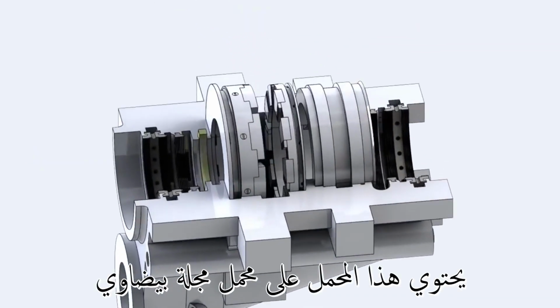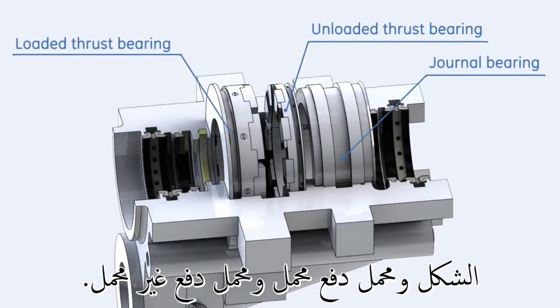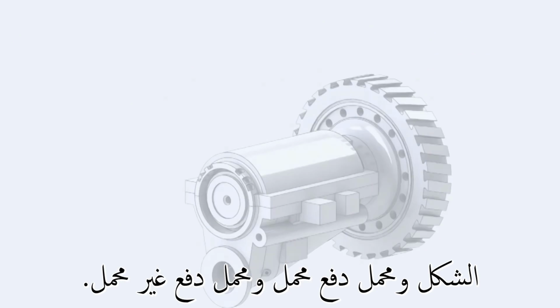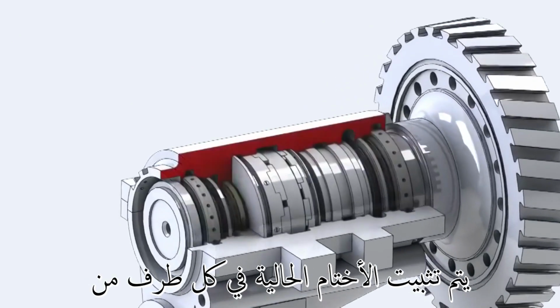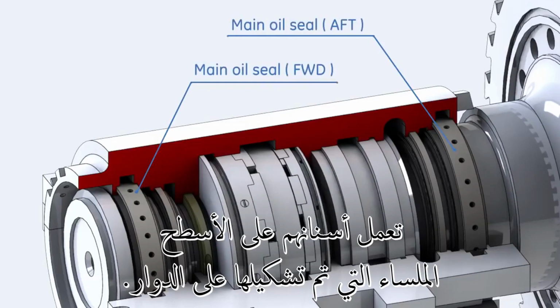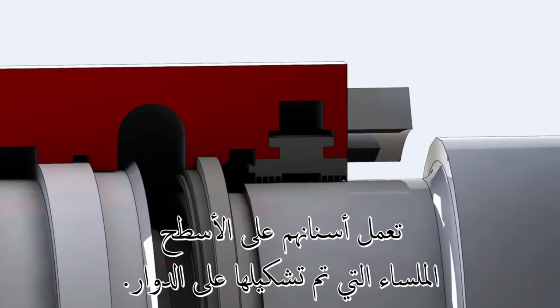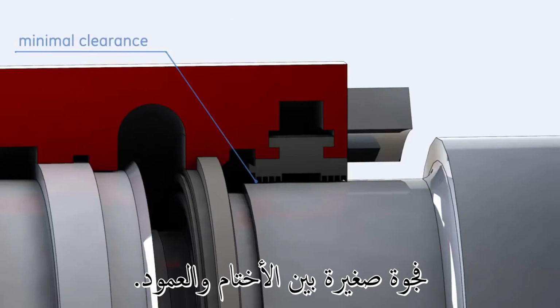This bearing contains an elliptical journal bearing, a loaded thrust bearing, and an unloaded thrust bearing. Labyrinth seals are installed at each end of the housing, where oil control is required. Their teeth run against smooth surfaces machined on the rotor. Seals are assembled so that a small clearance exists between the seals and the shaft.